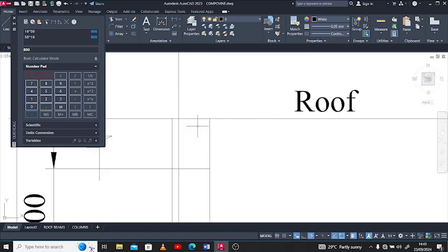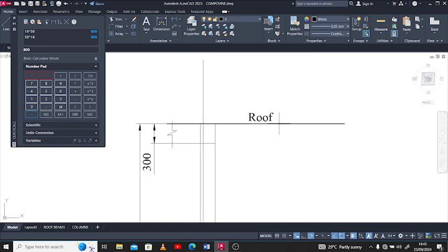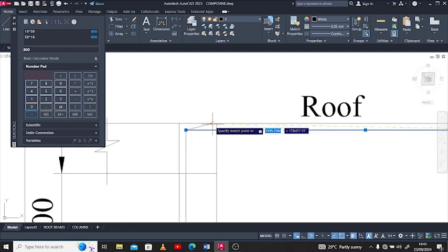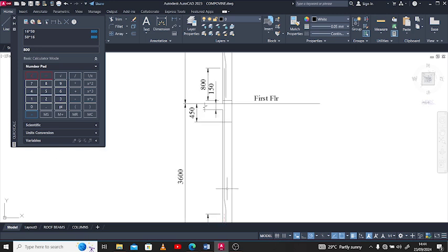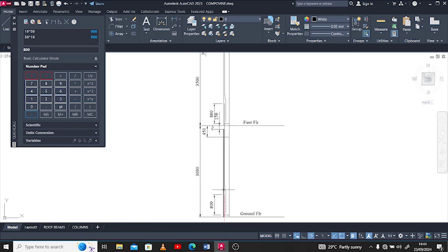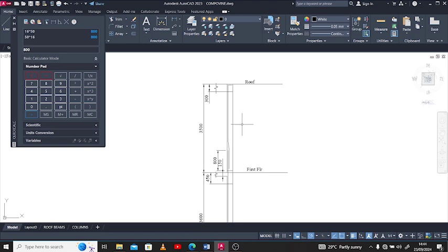Okay, now this level is the roof, so everything terminates at this floor. So I just want to create a cover at this point, which is cover of 40, then create a fillet around this point to show that it ends. Then I can have a little anchorage at this end. So this shows what my reinforcement will look like.